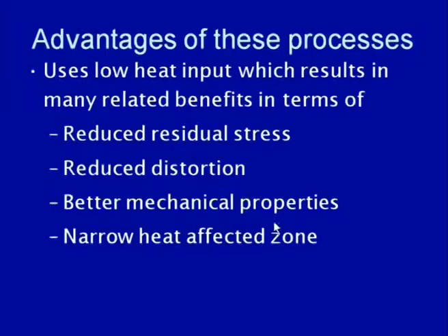So, the extent of variation in the mechanical properties of the heat affected zone formed in fusion welding processes is reduced, and because of that the deterioration in mechanical properties in braze welding of the base material is reduced. This in turn results in better mechanical properties of the base material, including in the heat affected zone. And as I have said, the heat affected zone is developed because of the excessive application of heat for fusion of the base material.